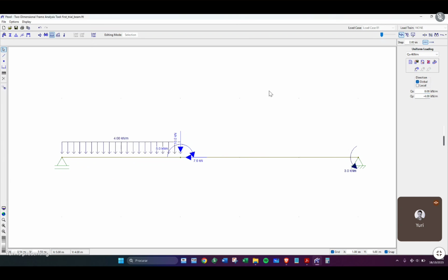But if you want, you can create multiple loads. Let's create another one here. For example, P equals 2 kilonewtons per meter. I forgot to click on per meter. Okay. And I want to apply this horizontal force in here, just equals to -2. Actually, it's 2. And then apply. As you can see, this section of the beam is going to be under compression by 2 kilonewtons per meter. Okay, so wow, this is pretty cool.